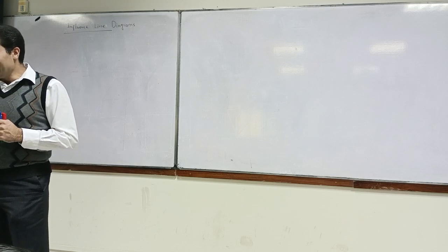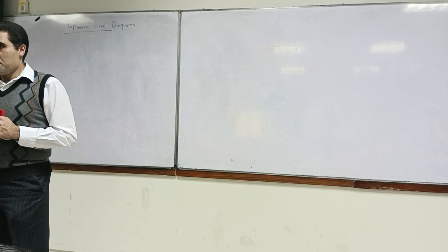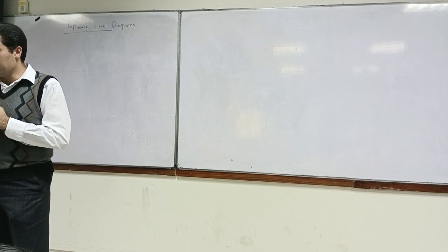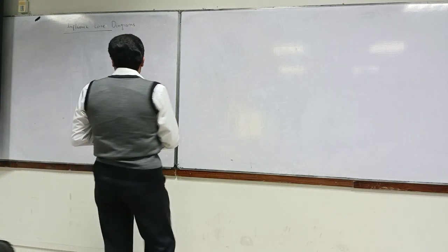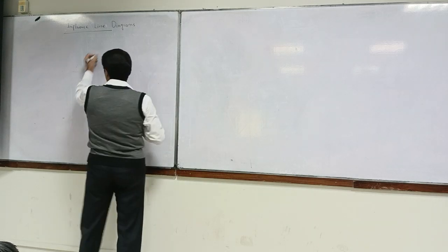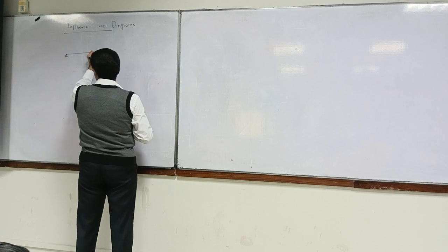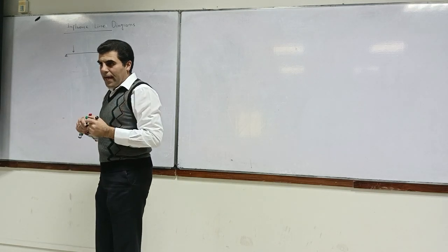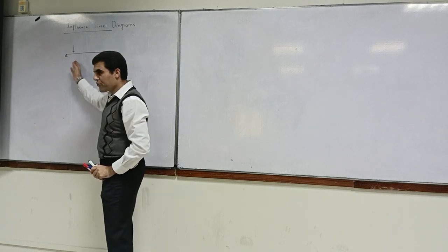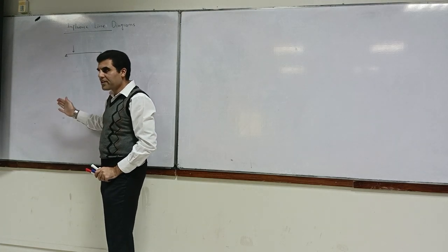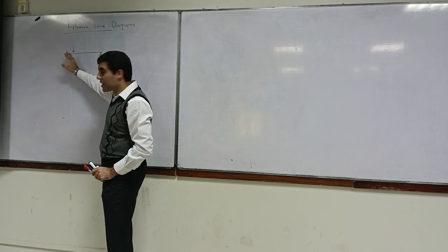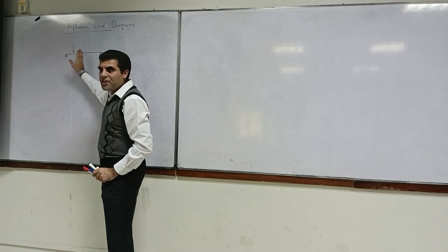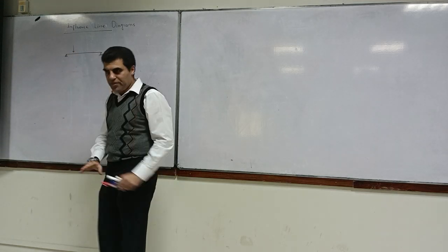So what happens is that we consider then the effect of that moving load on the structure. Now, for example, if I have a simply supported beam which is subject to some applied load, in the static condition it will give me shear force and bending moment diagrams, and we will study later in the course that you can find deflections also under this load condition. But you would appreciate that if I change the position of this load, my shear force, bending moment diagrams and everything changes, doesn't it?